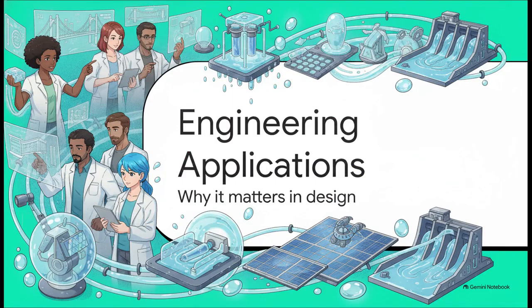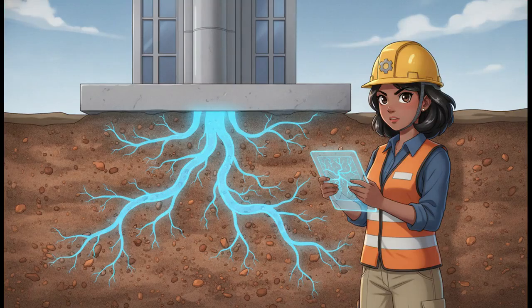Let's bring this into the real world with Part 6, engineering applications. In civil engineering, mastering these exact equations is absolutely non-negotiable. Think about soil mechanics. In fine-grained soils, like clay, the tiny pores between dirt particles act exactly like microscopic capillary tubes. Capillary rise in these soils can actually reach several meters vertically.